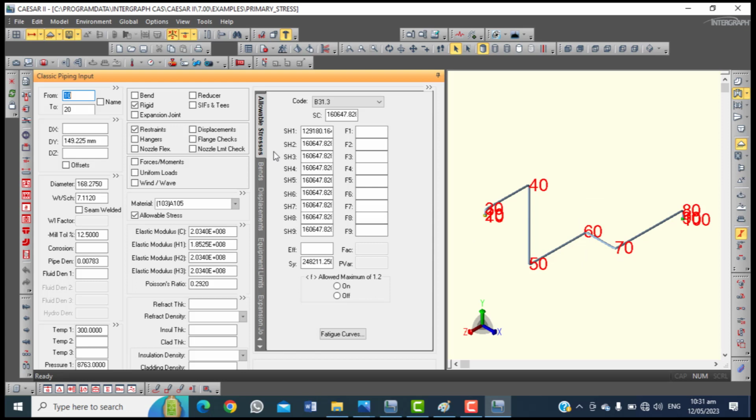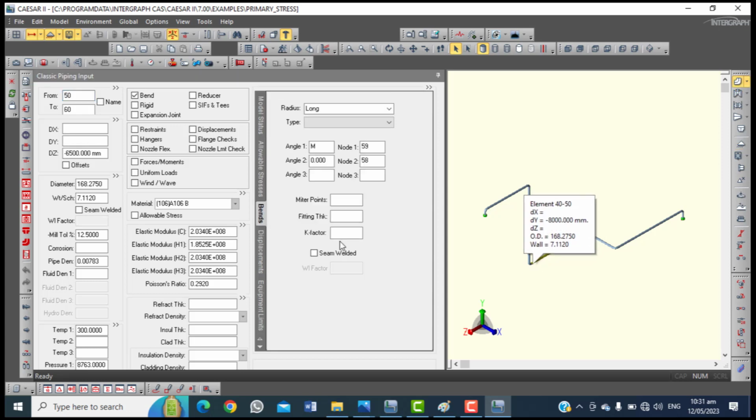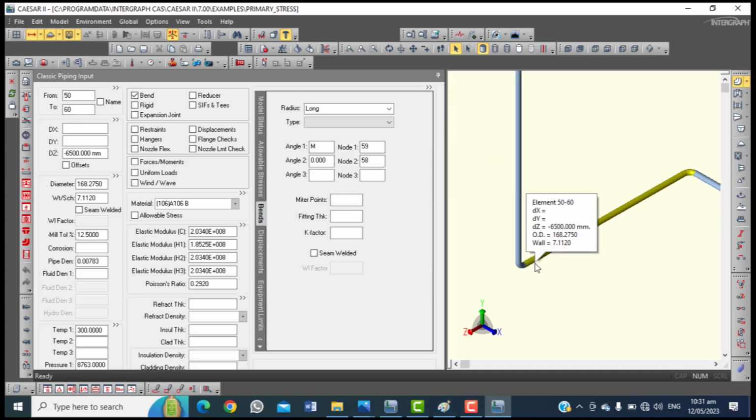And then see whether we would have the displacement reduced and the bending stress, which is actually what is causing failure, eliminated. All right, so what we'll do here is I will hit this element, select element, and let me remove the display node numbers. So I will click here. It takes me to element 50 to 60, right? So this particular one here represents element 50 to 60.